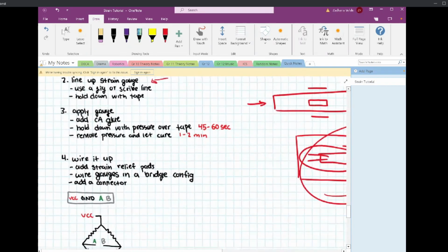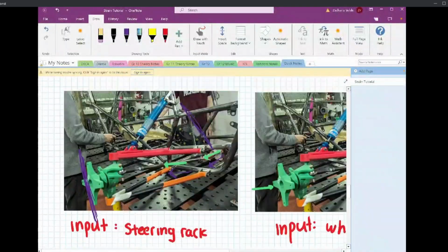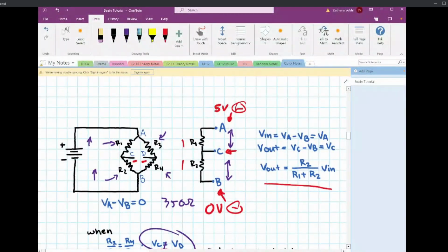And then you got to wire it up. In the beginning, we made this Wheatstone bridge setup off of the tube itself. And this made the most logical sense: let's just take all the resistors and take them off the tube, which is going to end up being like 8 wires. It's 2 for each, and then you deal with it afterwards. You deal with it on the board.